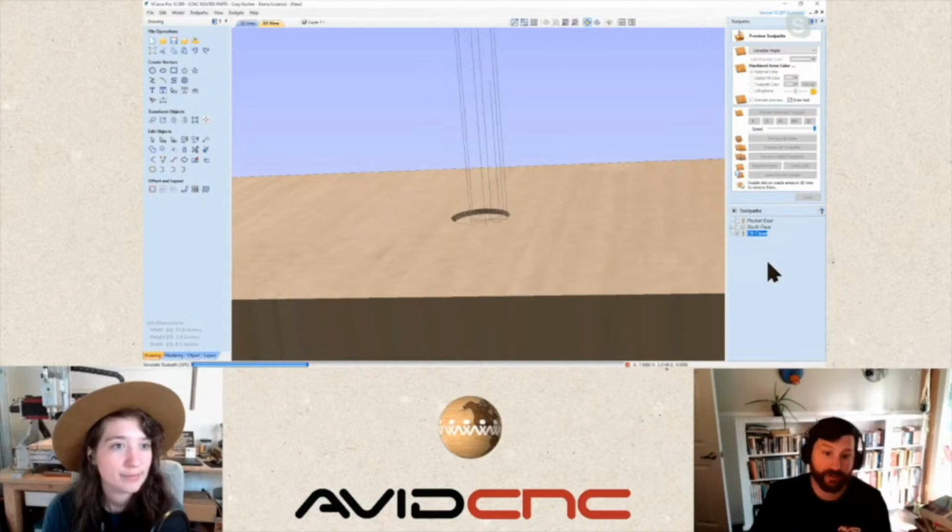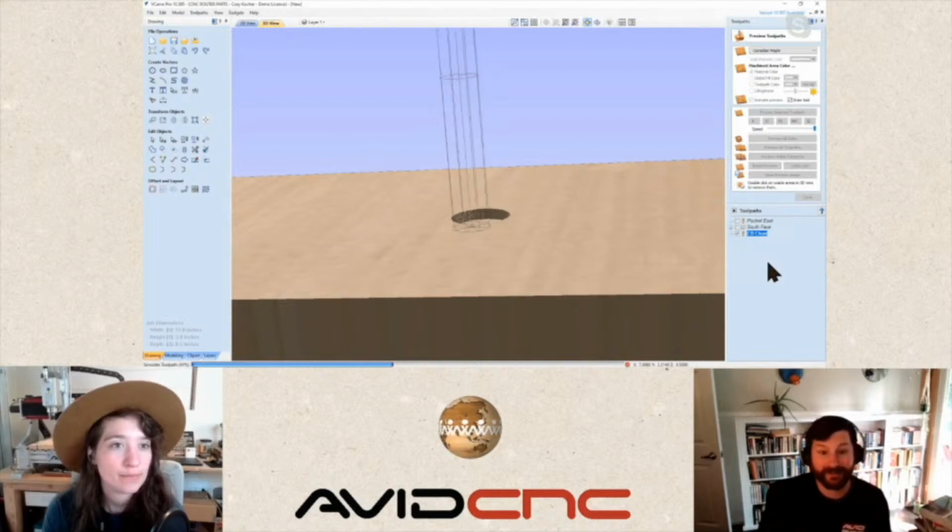And this preview is a little bit slow because our feed rate's a little bit slow. With our series machines, I'm usually in the hundreds of inches per minute when it comes to feed rates, and so the Vectric preview can seem very fast, because it is. And when we slow our machine down to a more achievable feed rate, it gives us a little better preview of what it's actually going to look like when we're doing those machining practices, right, Sami?